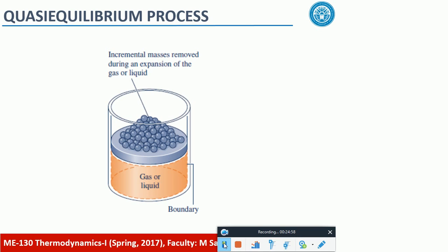If you put any word like this, I was talking about the wing. Generally, the theory which is applied on a static wing is known as steady state aerodynamic theory. If I try to apply that steady state theory on a rotating or oscillating wing, I would say that I am using it in its quasi-steady form. Do you understand that? Quasi means almost.